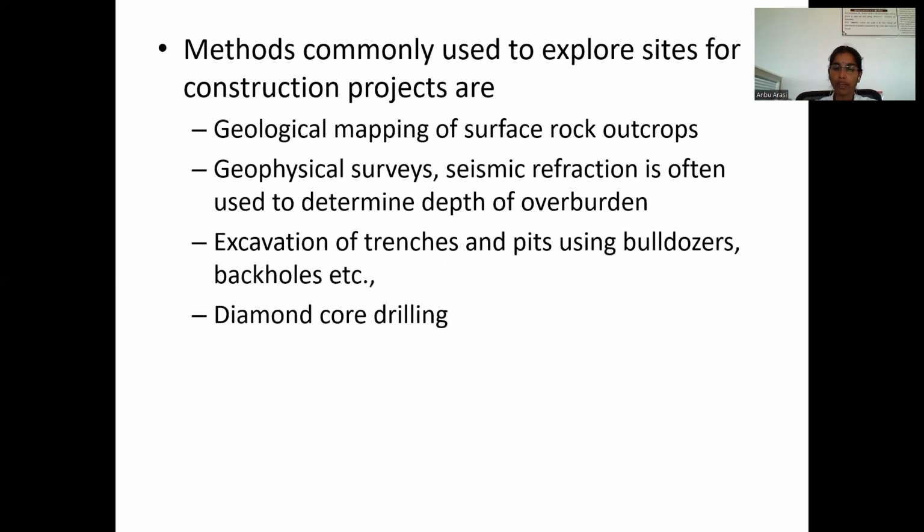Methods commonly used to explore sites for construction projects are geological mapping of surface rock outcrops, geophysical surveys, seismic refraction, which is often used to determine depth of overburden, excavation of trenches and pits using bulldozers, backhoes, etc. Diamond core drilling, as usually carried out, recovers an undisturbed cylindrical sample about 50 mm in diameter from depths of a few meters to hundreds of meters if necessary.